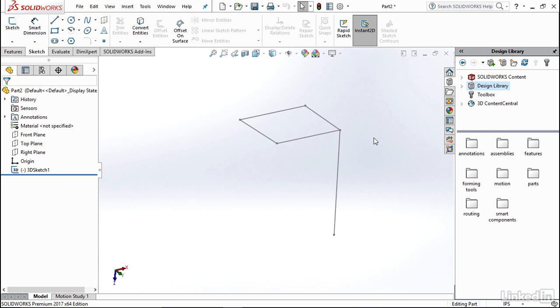And now I'd recommend trying to draw some more lines in this view to see the difference in how it looks, and just play around with the tool so you can get more comfortable before you actually use it to create some of your pipes. Keep these 3D sketching techniques in mind as we start the routes in 3D space. It will help you make sure your pipes are taking the path that you want.